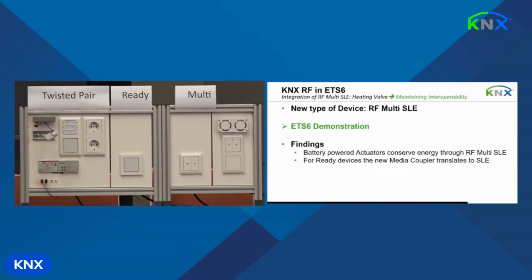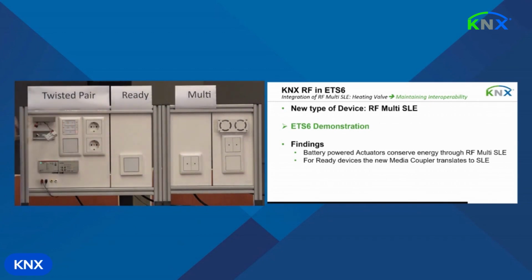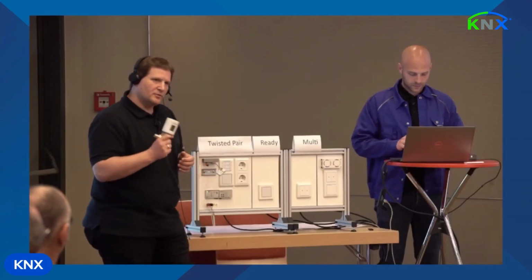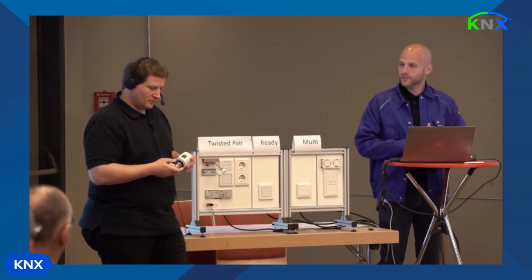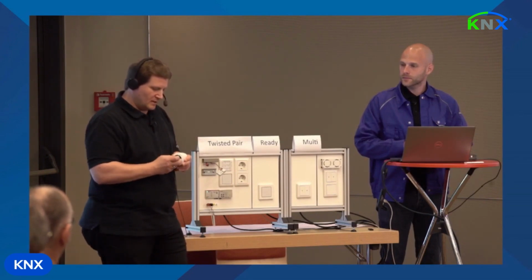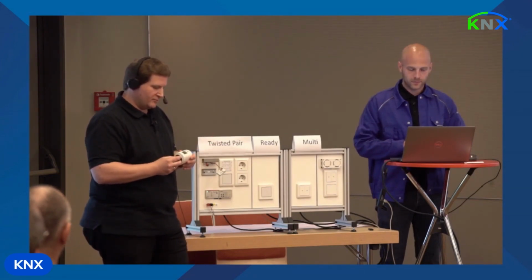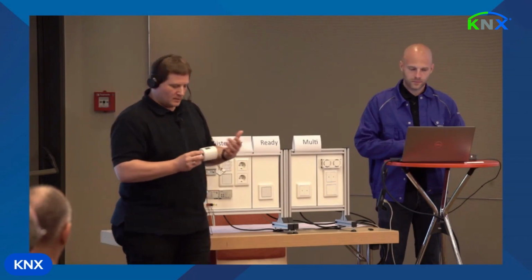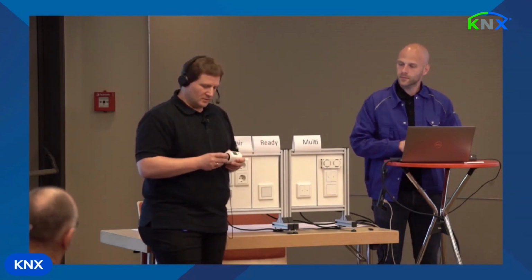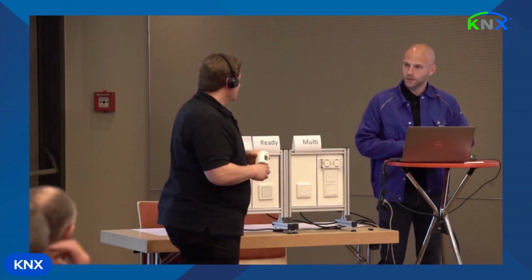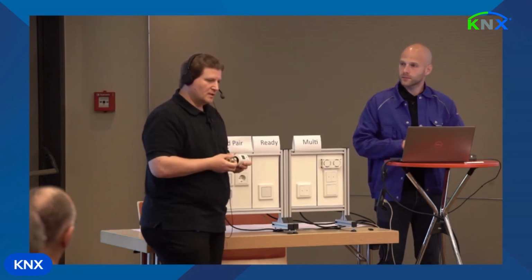Okay, so we have a new type of device, the RF Multi SLE device. Exactly. We have here a radio frequency multi device, battery-driven with the SLE extension. This means only with this protocol extension was it possible to build devices like this, which constantly listen to frames on the KNX network for receiving new current temperatures from the room, if it's not measured by the device itself, or changes of the heating mode. And these kinds of devices are listening all of the time with the multi-SLE extension.